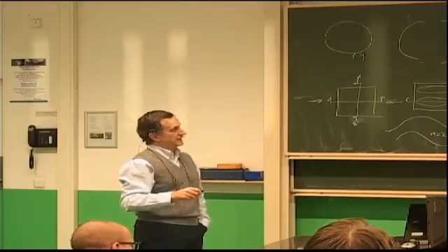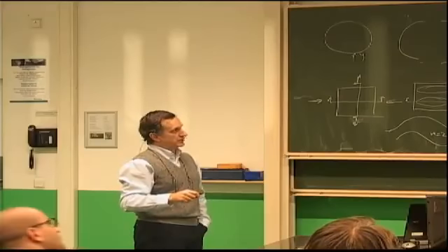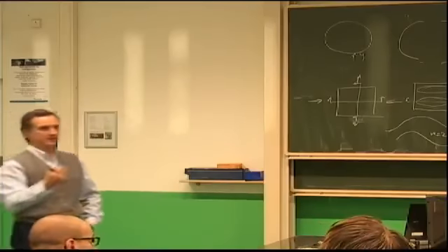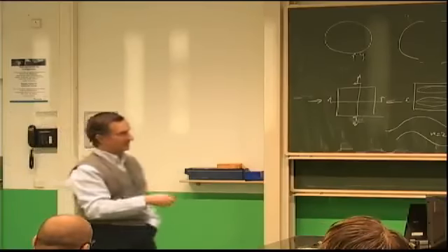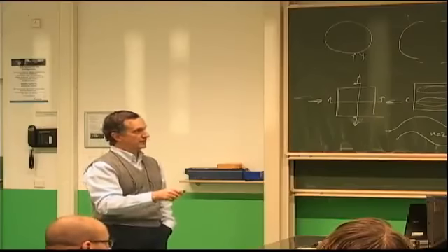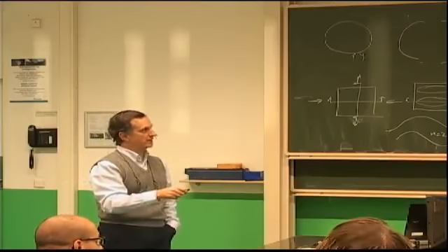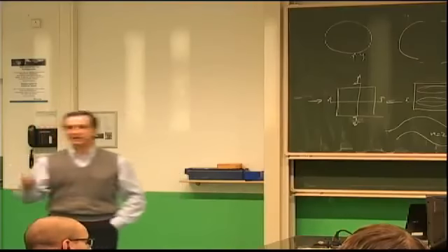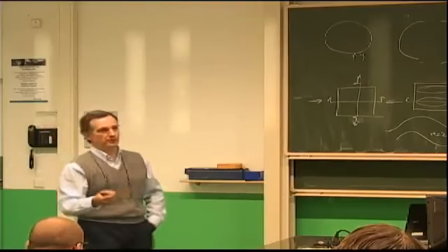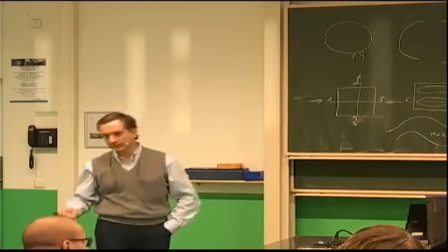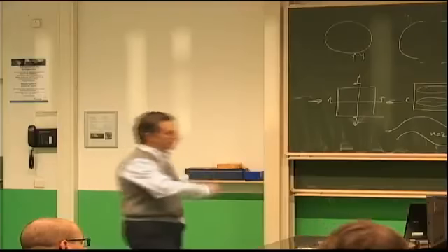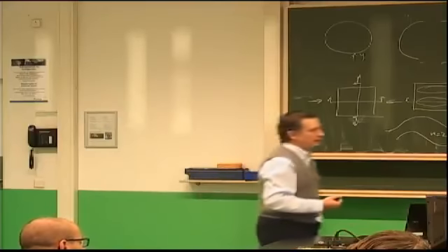Interesting is that at the intersections of these curves, the analysis says you have two buckling modes coexisting. That is, the structure should buckle at the same time with one half wave and two half waves at this point here at around 1.4. Obviously, in reality, it never happens. There are eccentricities and imperfections which will favor one of the two. And depending on those, you will go either on M equals 1 or M equals 2.